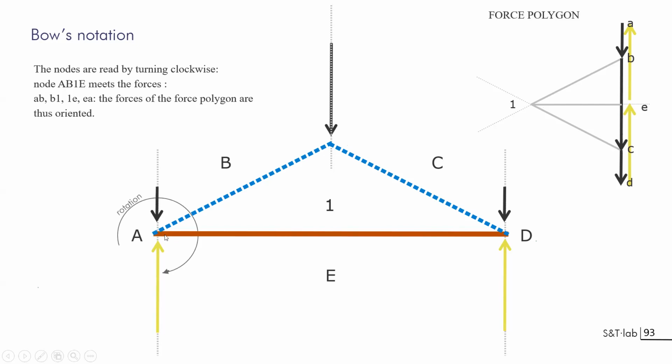That will be demonstrating that the bar is pushing on the node. On the other side, you will do 1 to B, 1 to B pushing in this direction. So the bar is pushing on the nodes by reaction. Second principle, you have to know that the node will be pushing on the bar, and this bar will be in compression. You can do the same exercise for each of the bars, and you won't be making mistakes about this.